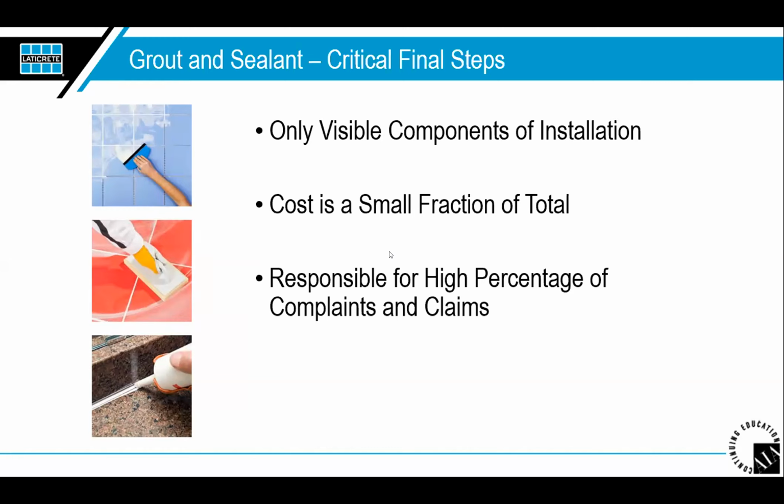Sealants must be specified in all corners, coves, and change of planes. And when I talk about sealants, I am talking about the actual 100% silicones, for example. I'm not talking about the unsanded and sanded caulks. Those are not to be installed in any corners, coves, or change of plane, and that's where we use sealants.